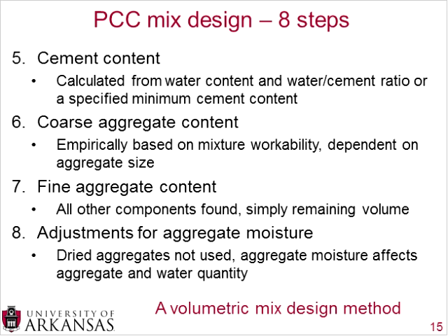When you're doing a PCC mix design, you do not want to use dry aggregates because all of the water that you put in during the mix design is based on the water cement content. And if that water goes into the aggregates, then you're losing water, and your water cement ratio will change, and your mixture will not be as optimized as it could be.